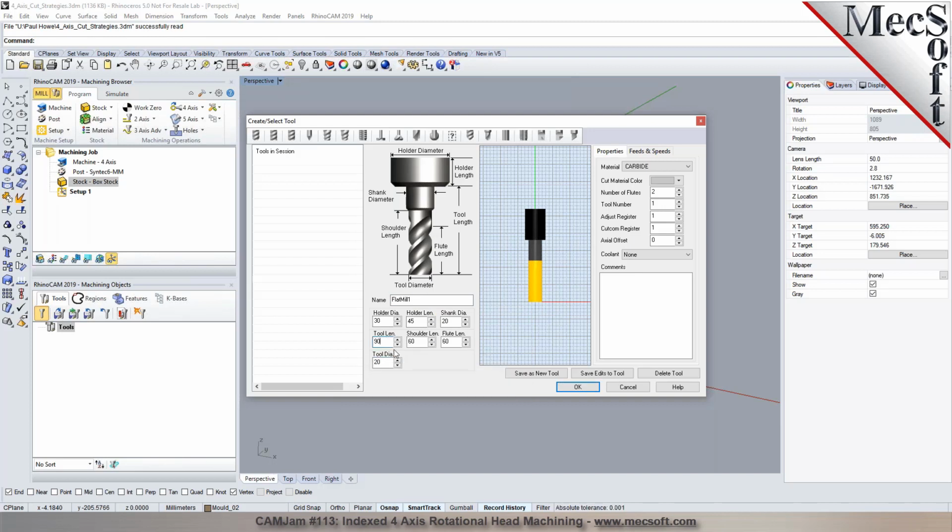And we can set the tool length from the tip to the spindle face. That'll add that to the gauge length when we apply a gauge length. So what you put in for the tool length has to be correct, the value, if you would like the cam to compensate for the gauge length. Okay. And then you specify the tool number.